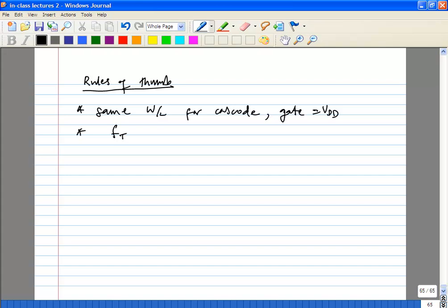The thing is like this: the larger you start off with, the more headroom you will have for your main transistor, and the better the IIP3 you will get. So you will make the decision to reduce it only after you are sure you meet your IIP3 requirements. When you start off, you don't know what your IIP3 is, you don't know anything about the LNA, except that you know the noise figure. You know the power consumption. Those two things you know, but you don't know much more.